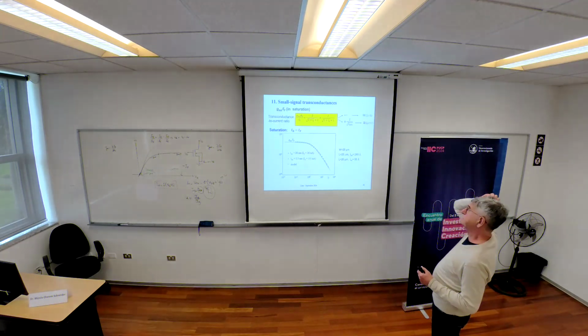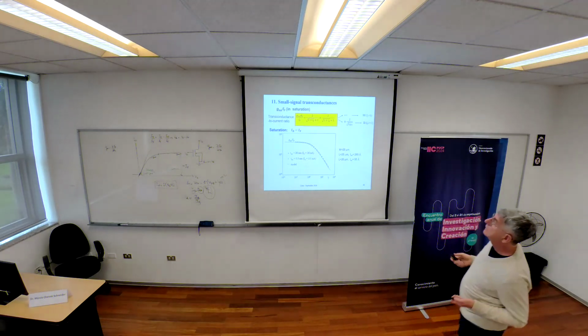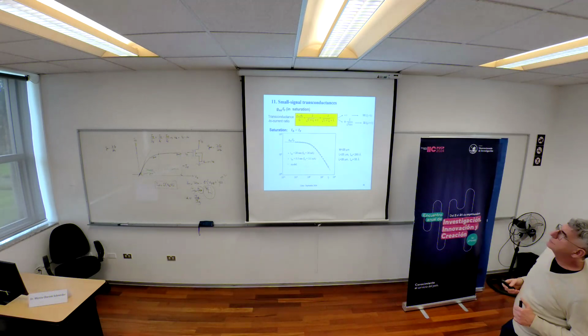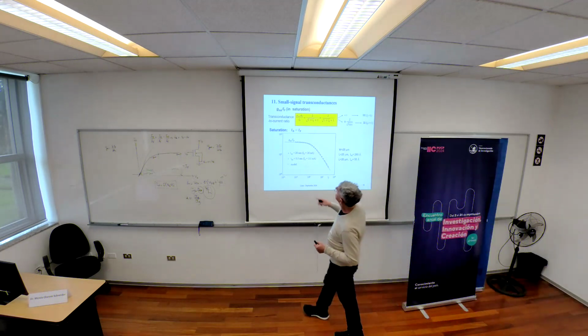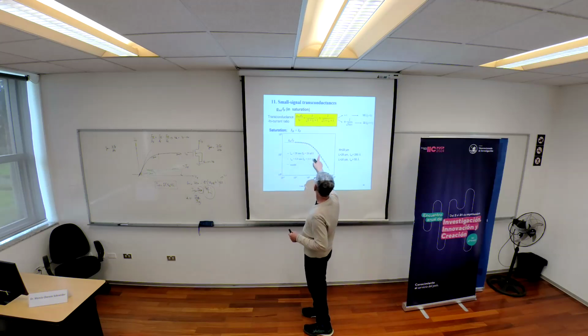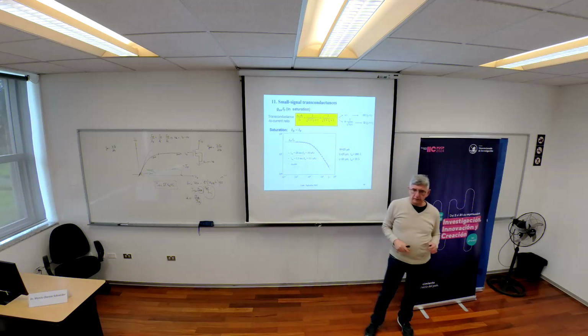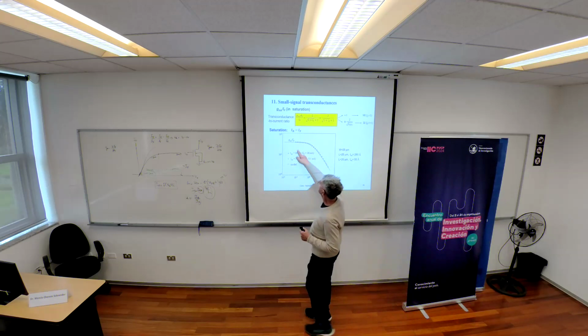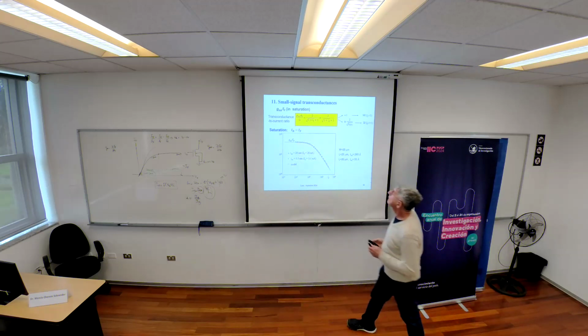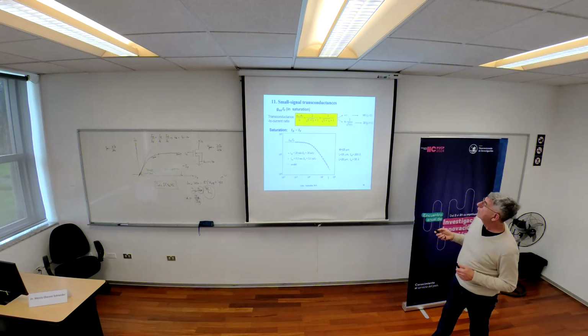This is another curve, which is the GM over ID, or if you want, GMS over IF. The theoretical curve is this one here, a solid line in this picture. These symbols represent measurements. This is for a transistor in saturation.